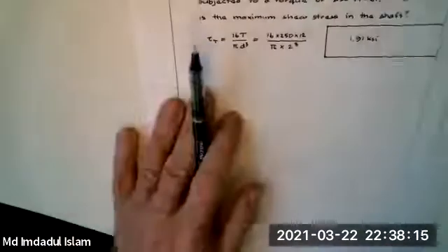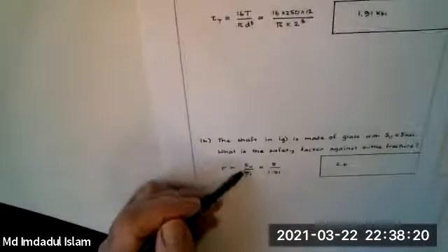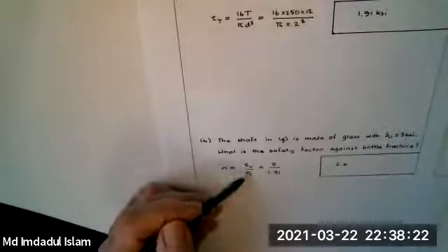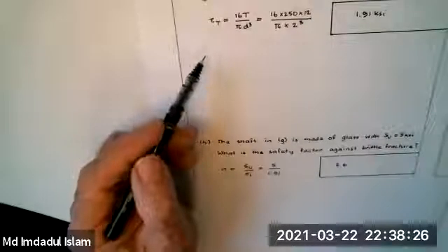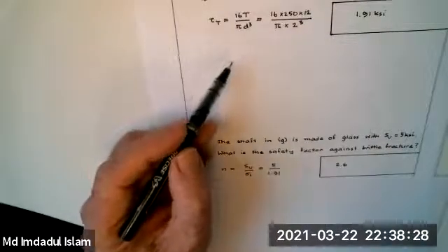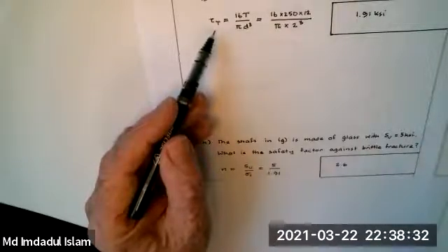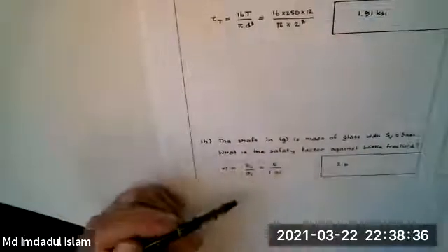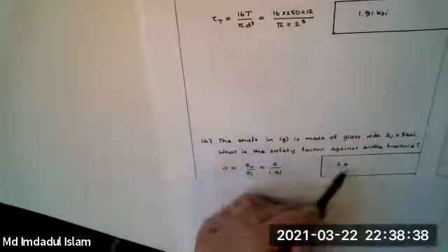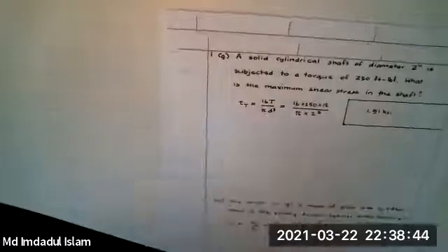Now, to get the safety factor, this is brittle. It's SU upon sigma 1, where this is the peak principal stress. When you just have tau T, then sigma 1 is sigma A plus or minus tau T. Tau T is tau max. There's no bending here. And so sigma 1 does equal tau T, so you get 2.6. Again, for a safety factor, you just need 2 figures. But you can give extra figures; you wouldn't be marked off for doing extra figures.